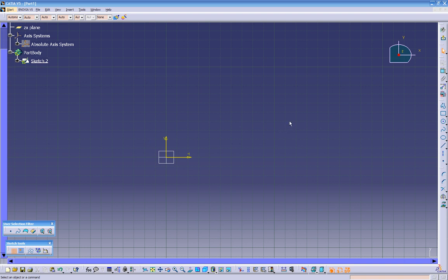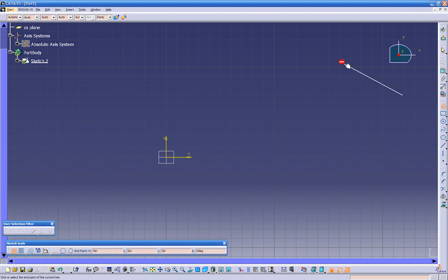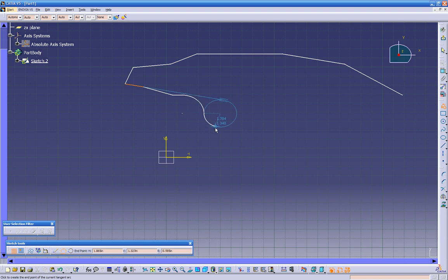So we can create just a quick rectangle. Click on the rectangle. You see we have quite different options over here we can create. It's a profile. This will create multiple lines. If you just snap it, you can create a line. But if you snap and hold it, it creates an arc. So snap and hold, then a quick tap goes line, line, line.